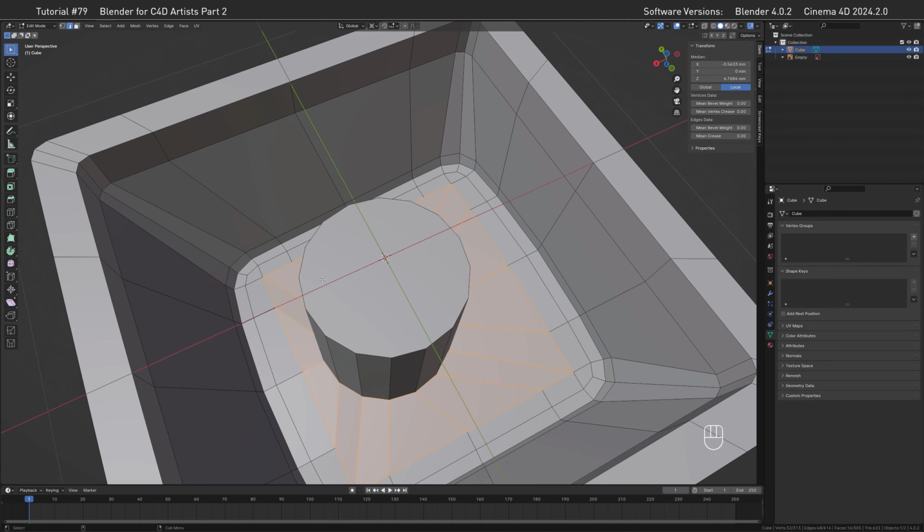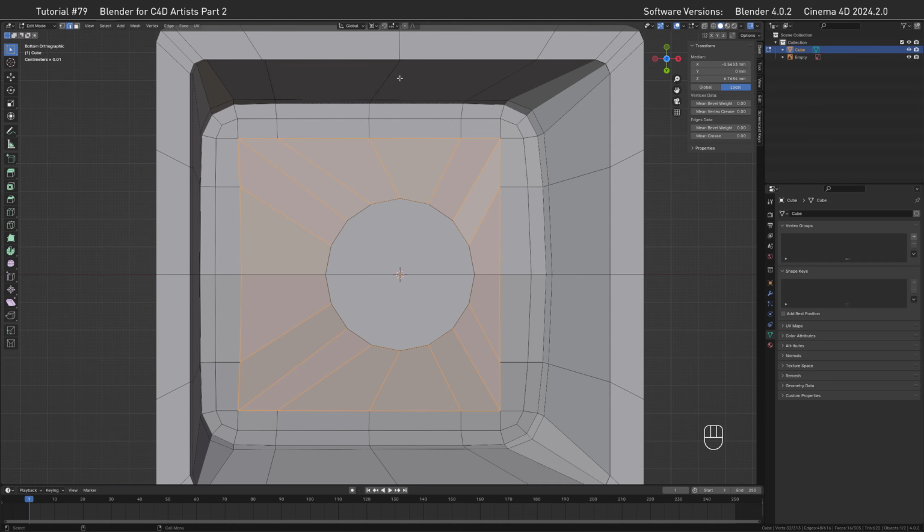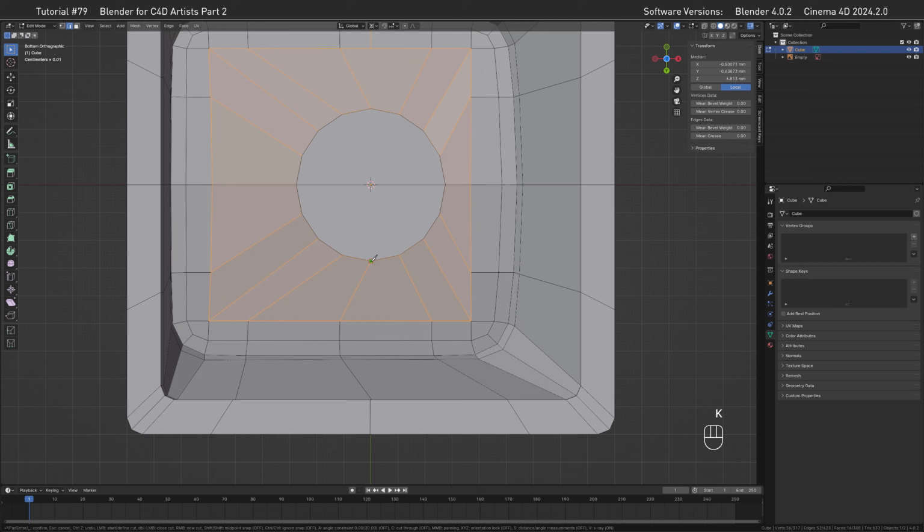So what I want to do is go and hit the tilde key and go to the bottom view here and then cut along here and here. So let's hit K for the cutter tool and we can snap to a vertex and then cut. Right now we are cutting loosely, but we want to snap it to an axis. So down here there's a plethora of shortcuts, and this is tool dependent and it tells you all the shortcuts you can use. So for us it's A to snap to an axis, and then we cut to there, then enter to get this going, and then again for the other side, cut A, and then to here, enter.